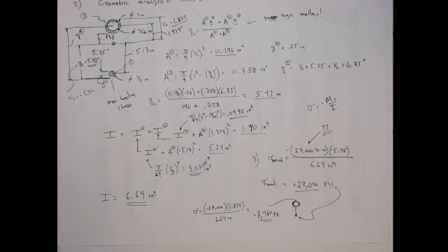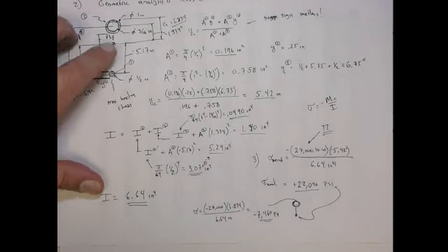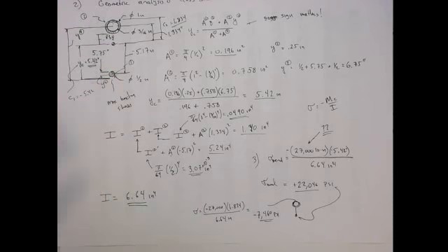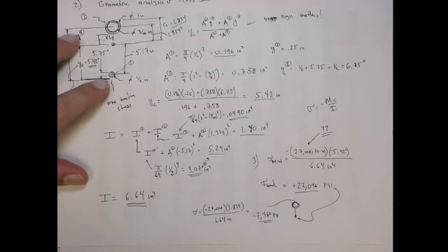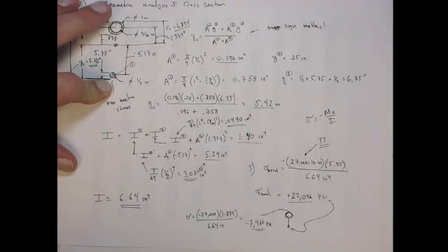So what's interesting to note here is that by doing this, putting a smaller area and shifting it so that we have this imbalance in I, so we have a non-symmetrical cross-section, you're able to control whether the maximum stress will be on the tension or the compressional side, okay?